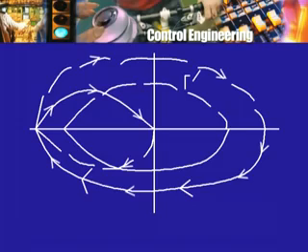So, this corresponds to the upper half of the j omega axis, frequency increasing from DC to a very high frequency. Then this blob here corresponds to the image of the semicircle, which is virtually the origin itself. Then I am coming to the lower half of the j omega axis. As the frequency is very high, I am here, and as the frequency is decreased to DC, I go this way. So, this is what is going to be the entire contour gamma prime.